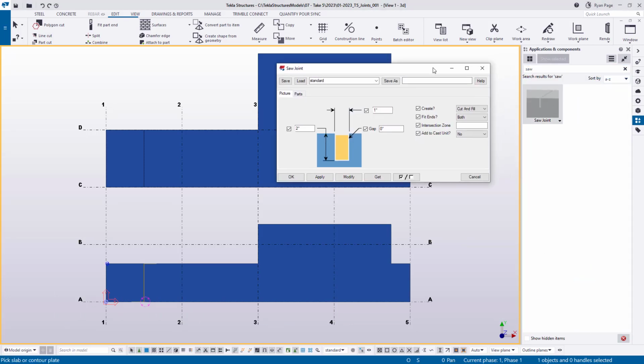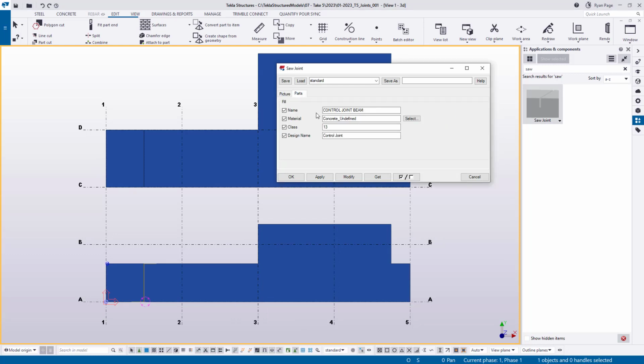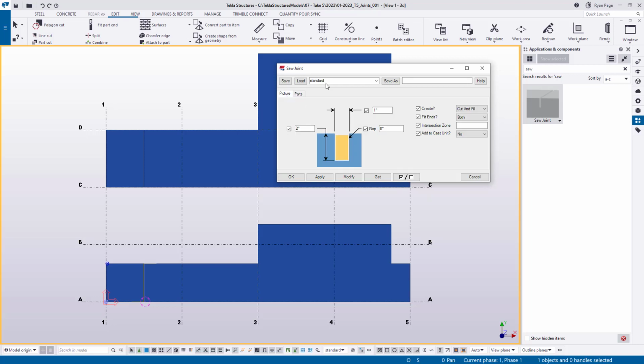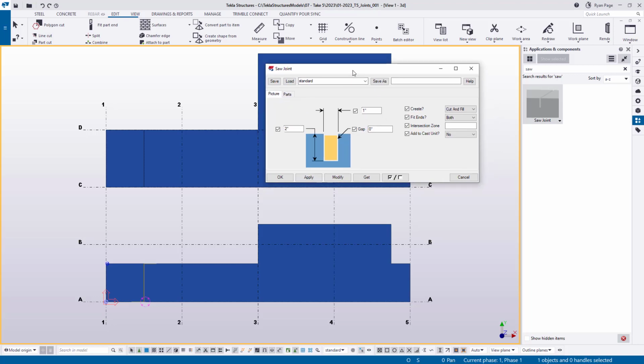Now, this tool is pretty good, and it creates similar results to what we have just been demonstrating: the profile, the cutting part, as well as the cut itself. And you can even define some of the parameters right in the tab. But the problem with this tool is it creates a precast piece of concrete. And if you're using the cast in place detailing rule, that's not going to play well with a lot of the default settings, such as reports or the organizer and things like that.